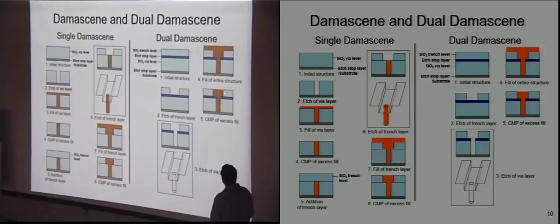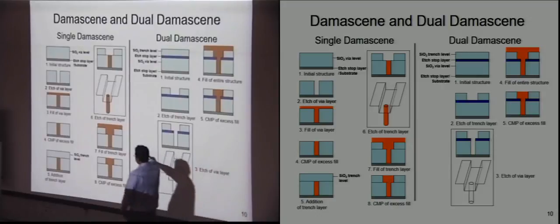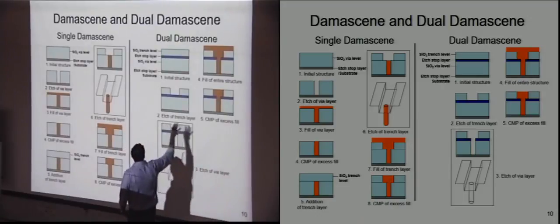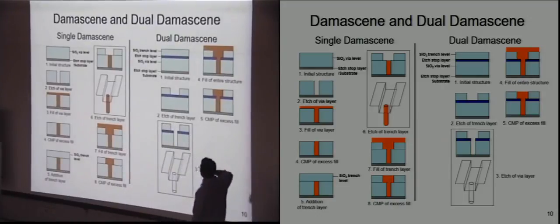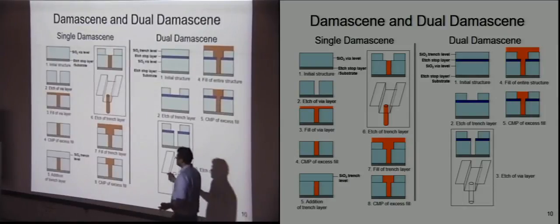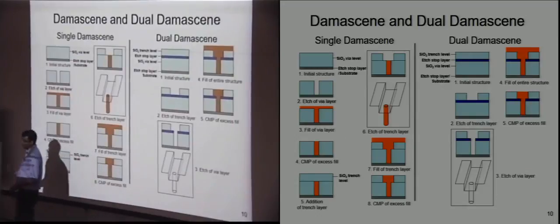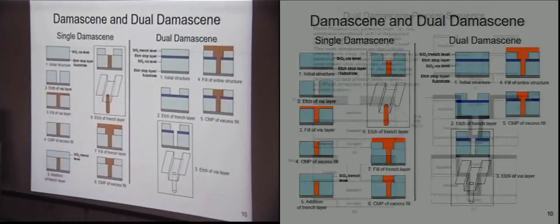Okay. So, this is the way in which instead of doing 2 times of patterning, more number of filling up the layers and starting one by one, here you start to condense it and try to combine the number of processes together. So, this is called the dual Damascene process, whereby you fill in a trench and a via at the same time. People do a lot of variation of these kind of processes, but effectively you are trying to fill it up in a very nice manner.